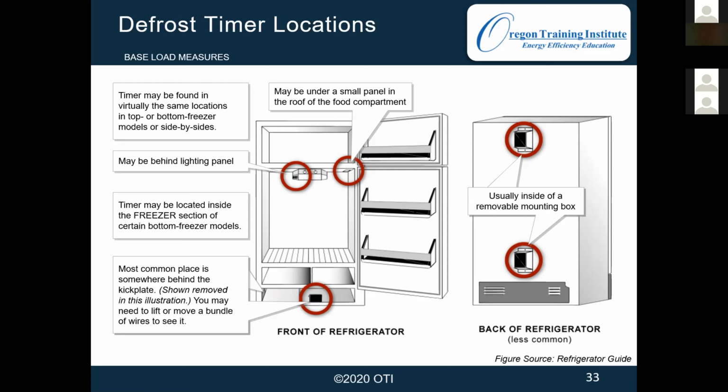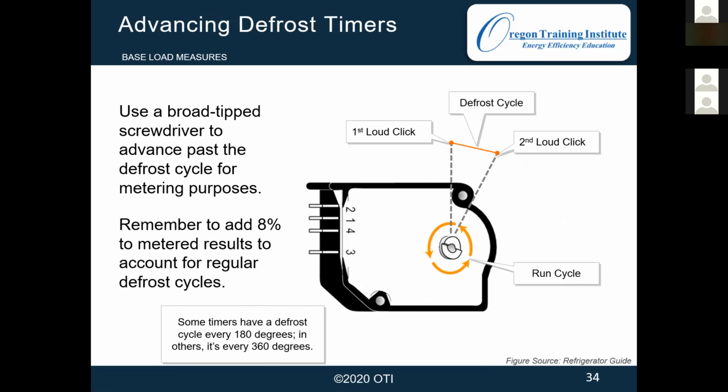If it went into defrost, then the peak wattage is going to be several hundred watts, while the average use or the normal use is going to be maybe 100 watts, probably less. And if it does kick into defrost, you're going to have to do the test again. So here's just kind of an explanation of how to cycle this into defrost.